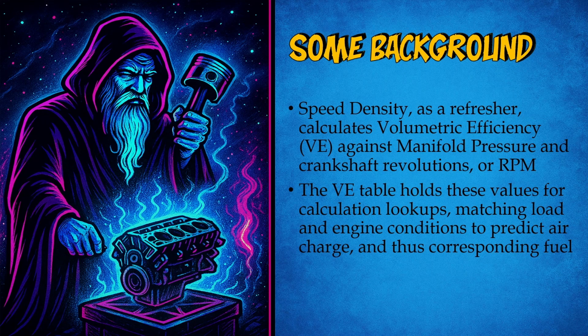Sometimes, as you get lost in the weeds of particular things, it's helpful to ask, why are we doing this? Because we're optimizing fueling calculations, right? So to do this, in previous generations, if you wanted to do speed density tuning on a Mustang, what you had to do was go out and get you a Bosch sensor, a MAP sensor. A 3-bar MAP is better, because what if you put on a supercharger down the line, right? Prep for forced induction. You would go and get this sensor, plumb it into your intake manifold where you get a good vacuum reading, right? Or at least the pressure reading at any given moment.